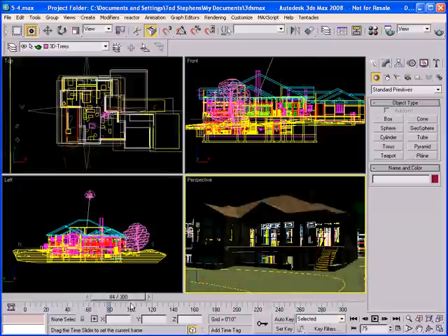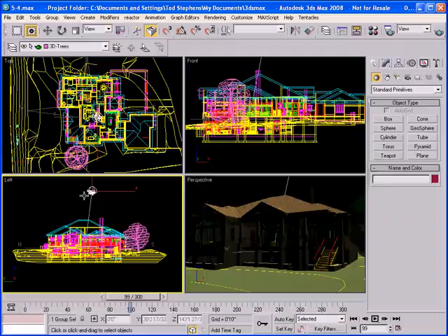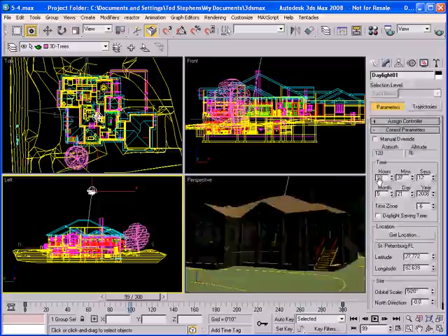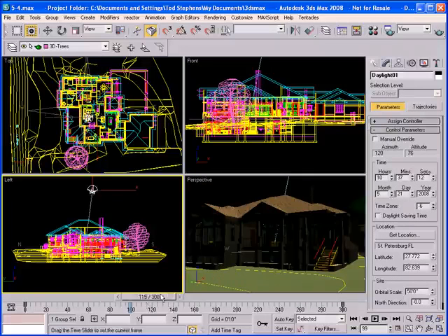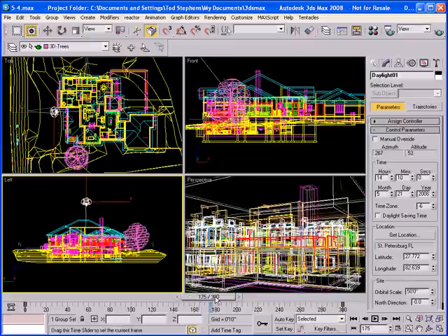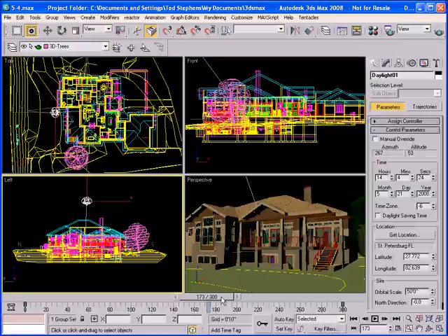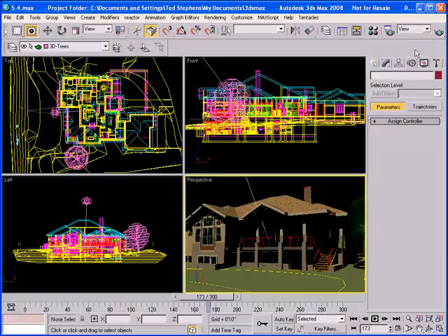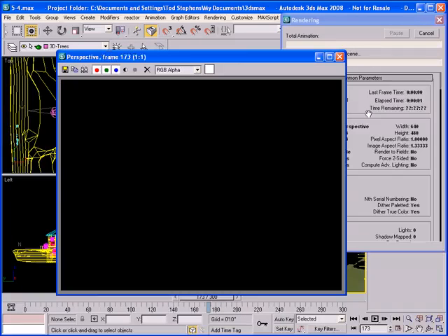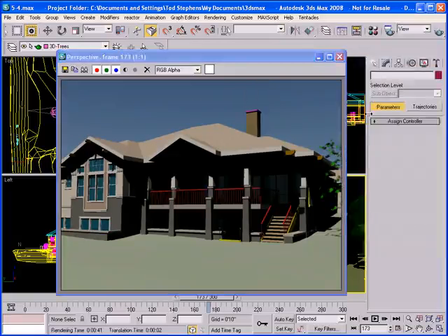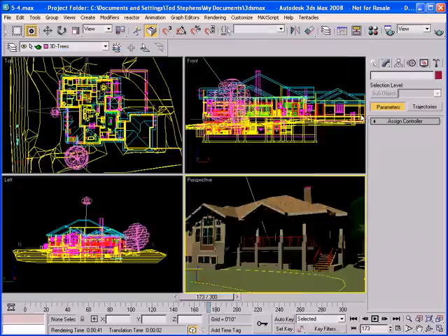So I'm just going to go to a frame and do a test render. Some just after noon or so probably here. Let me check. If I go under the setup of my daylight system, and under hours I'm at like 10 a.m. Going to go a little later in the afternoon. And just so the front of the building is lit pretty brightly, just to do a test render to see how fast it's going to render. I want pretty fast render times. With final gather off, it's lower quality, but it doesn't matter because I just need to be able to render quickly. And that's pretty good render time.